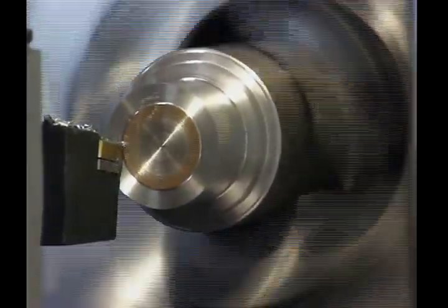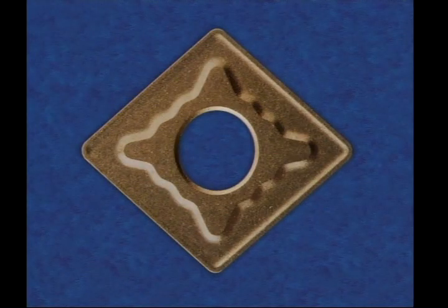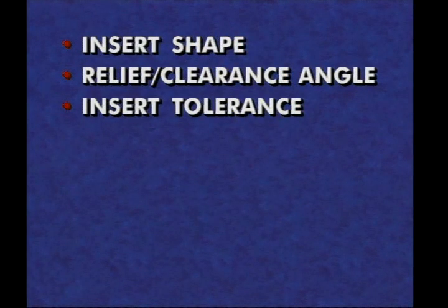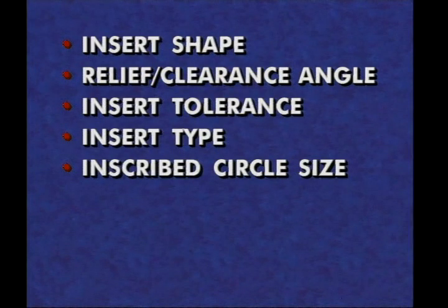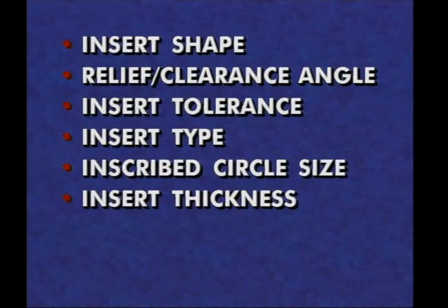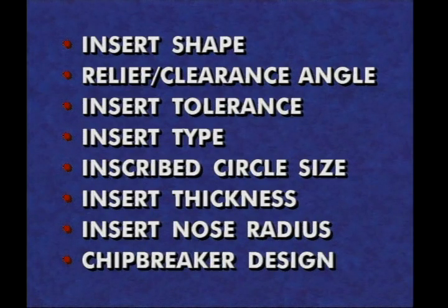But let's focus first on inserts. The geometry of an insert includes its shape, relief or clearance angle, tolerance, type, its inscribed circle or IC size, thickness, nose radius, and the insert's chip breaker design.